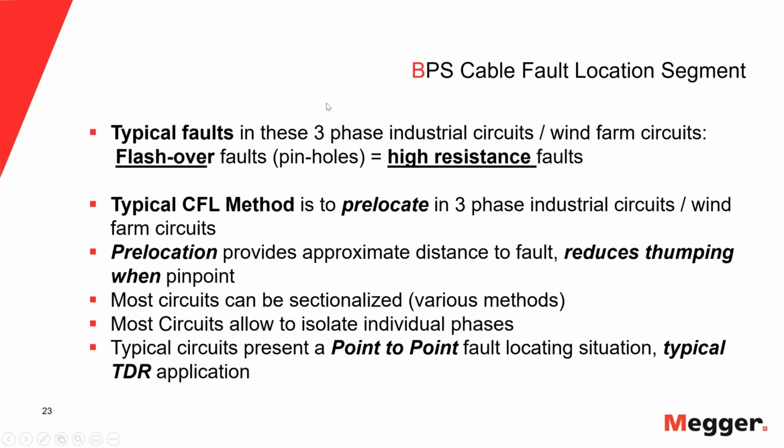What are the typical faults that you have after going through the pre-screening? What are the typical faults we expect in three-phase circuits with solid dielectric cables? For the most part, those are flashover faults, high resistance faults.